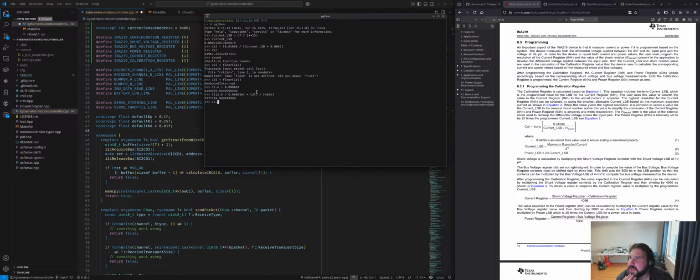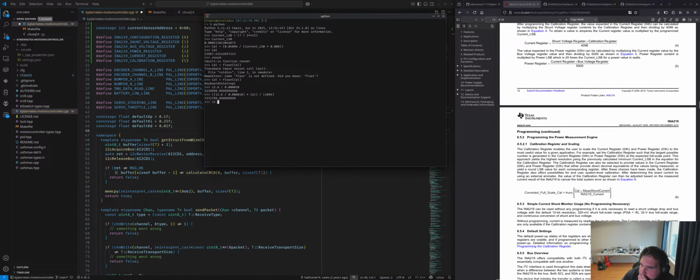How do I know what gain I want? That's the real question. The INA can be used without any programming if it's only necessary to read the shunt voltage drop and bus voltage with the default 12-bit resolution, 320 millivolt shunt full scale, divided by 8, 32 volt bus range.